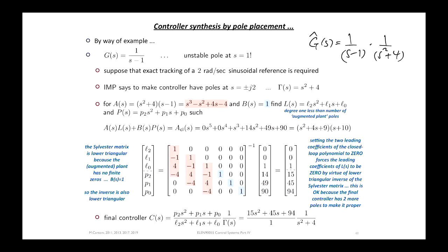Right, but this is just illustrating how you can exploit degrees of freedom in here to reduce the complexity of the controller, given that we've already specified this as part of the controller to meet steady state specifications. Right, and you don't have to do this. I could put 2 more faster poles in here that would make those non-zero, right? Just that my controller now would be more complicated. It would have 4 poles instead of 2. That's all. All right, but you can't always do this. It's really relying on the fact that B is special here.